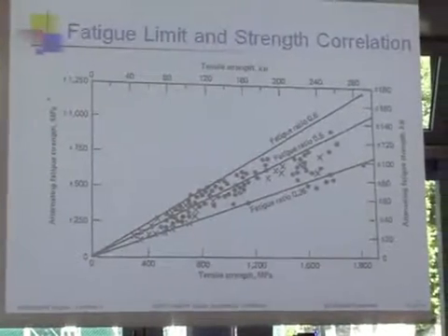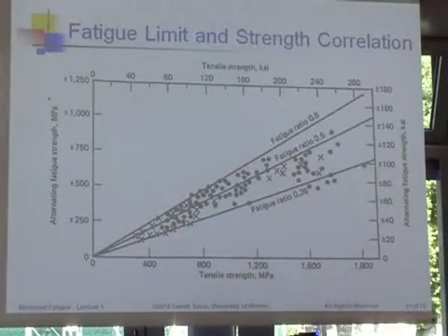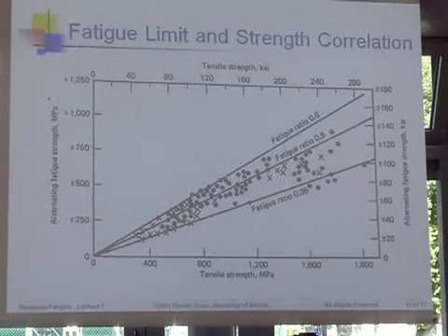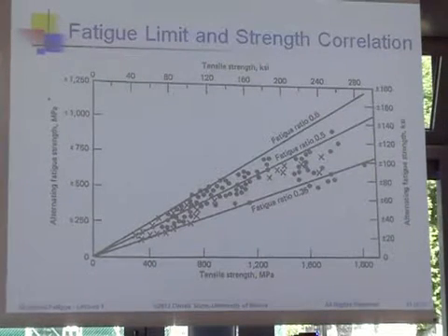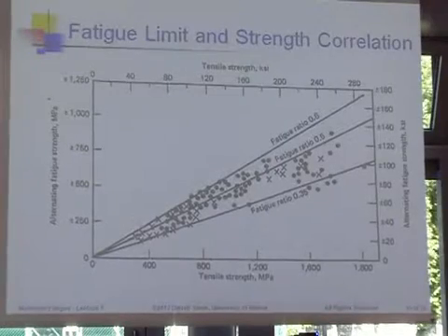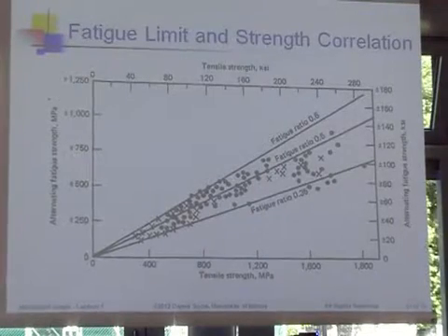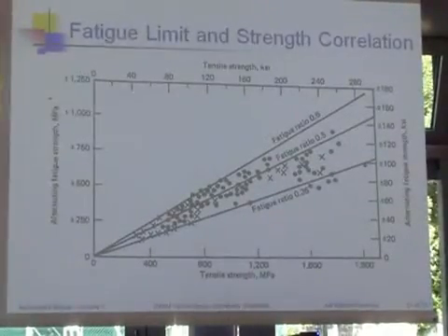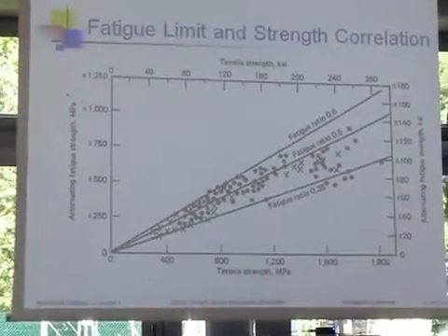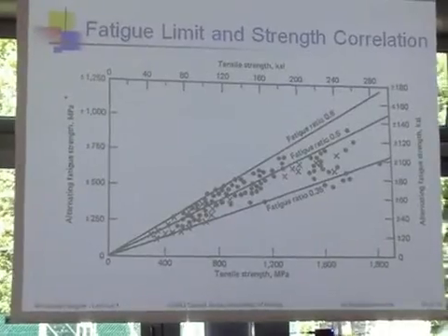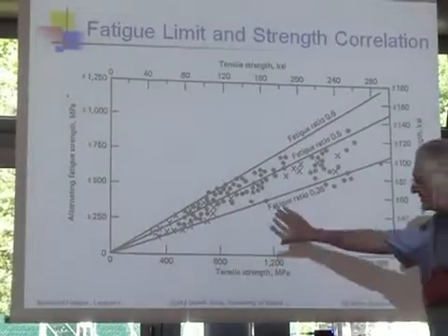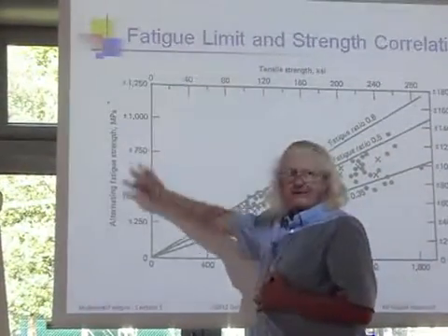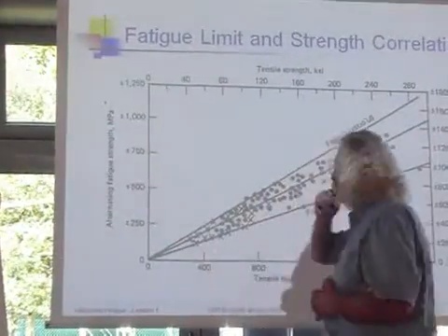Okay. So that's the basics of how fatigue starts and how it gets there. It really does happen at the microstructural level. I keep saying driven by shear stress. And this is the classic diagram, which is in machine design texts everywhere, except in the machine design text they never put the data points on it. They just put the lines there, and of course we know, in general, as you increase the tensile strength of the material, you also increase the fatigue strength of the material.